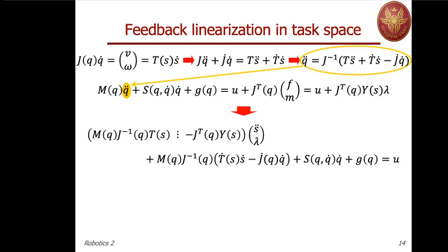And now we can reorganize things. So we replace this, and we reorganized, in fact, the inertia matrix. Now, when we substitute Q double dot, we will have acceleration terms in terms of S double dot, so we will have M times J to the minus 1 T. Now I'm reintroducing dependencies for clarity, times S double dot, and then we will have the parametrization of contact forces.